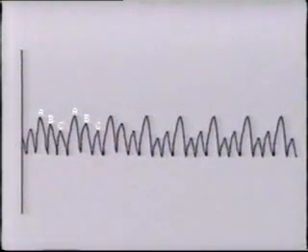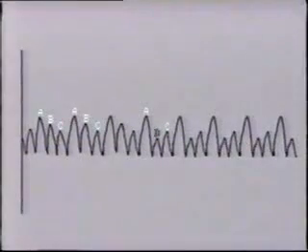The scaling which represents voltage is different for each phase, so that we can easily differentiate. In this trace, the A phase appears to have the highest peak, followed by B, then C. As a matter of fact, this oscillogram shows the incidence of a fault. Look here, the B voltage has decreased, while A and C remain normal.